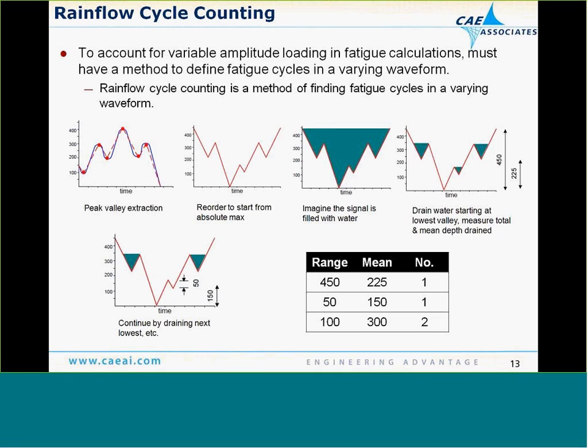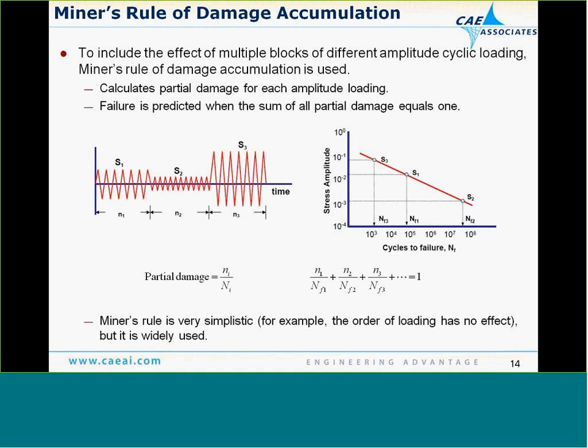And rainflow cycle counting will automatically go through any complex load and provide nCode with the definition of a more organized type of loading, cyclic loading, that it can then use in the analysis.